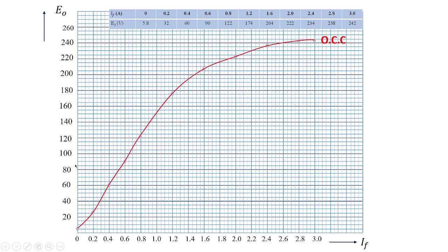Fine. Our intention is to find out the critical speed, critical resistance, and the voltage to which the no load voltage has reached with the help of the resistance. So what is the resistance value given? The resistance value is given as 114. So for point 1, 114 would be over here. So you can see this is 114 we need to obtain. So 114 can be obtained approximately as voltage 114 divided by current 1. Voltage by current, that is 114 divided by 1, is nothing but 114 ohms.